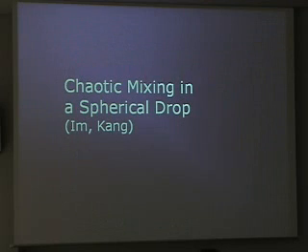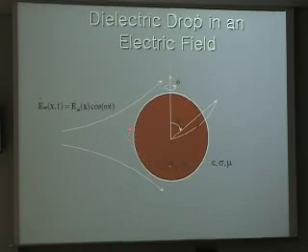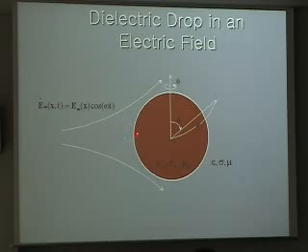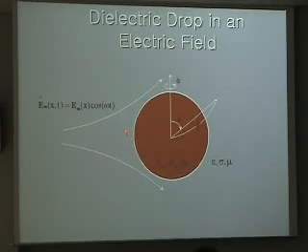So we may use dielectrophoretic forces to generate circulating flow inside the block. Because at the interface we have two components of the surface forces. One is the normal component, the normal stress part, and the other one is the shear stress part. So the electric field generates electrical shear stress.